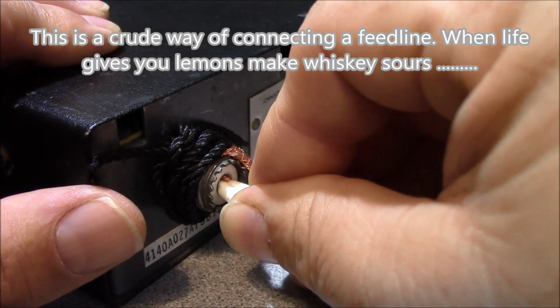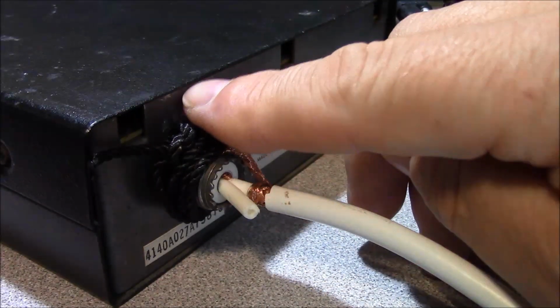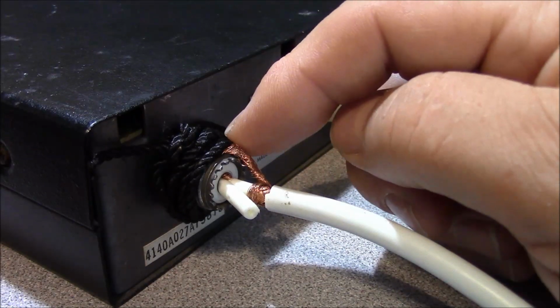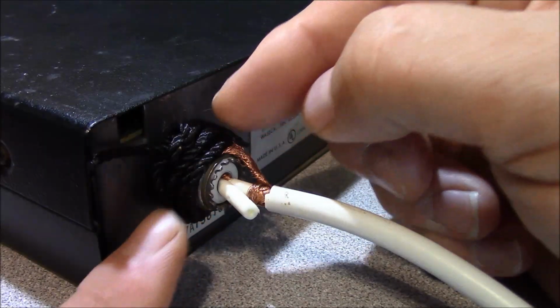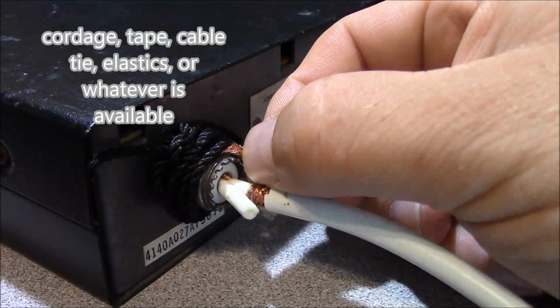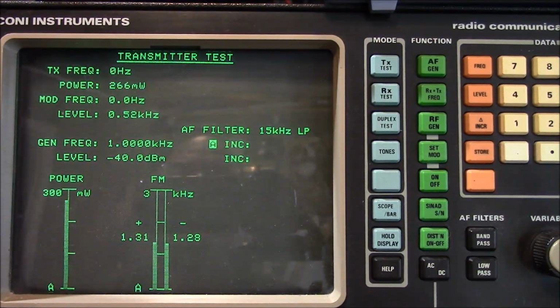And then, all I've done is just cut my dielectric back, and you just shove that in there, and that shims it up. Take your shield or your braid and either shove it between your chassis and the cover on the radio, or wrap it around the RF connector, or just do what I've done here. Just lay it on here, tie a simple clove hitch on top of that, and bundle some cable on it, and it makes positive contact with the chassis of the radio. Not perfect, but it works.